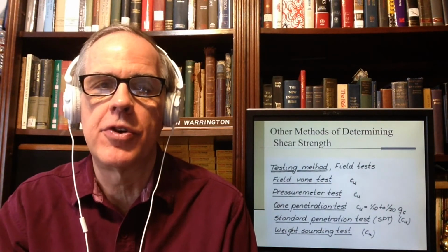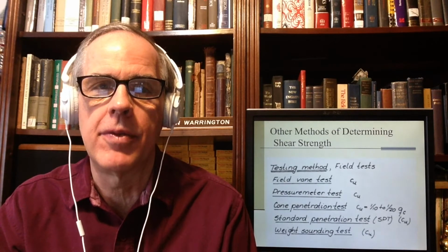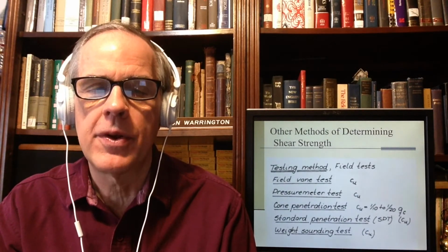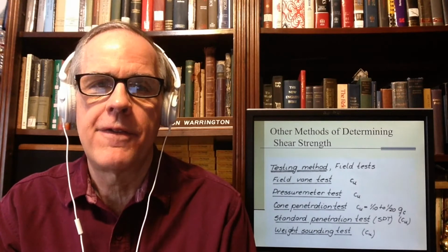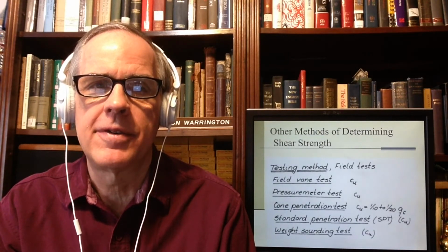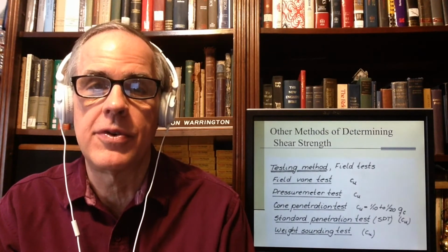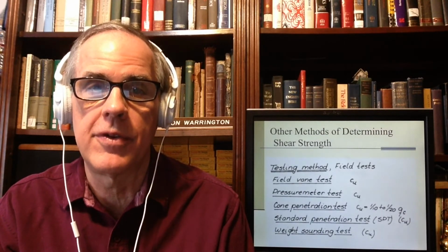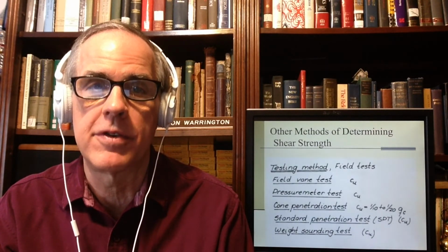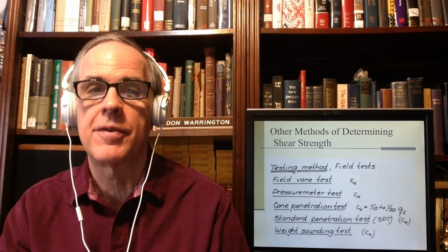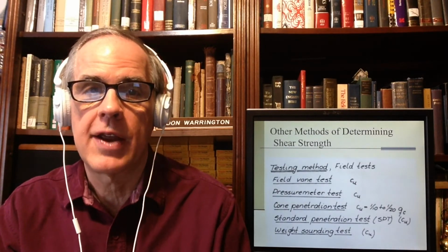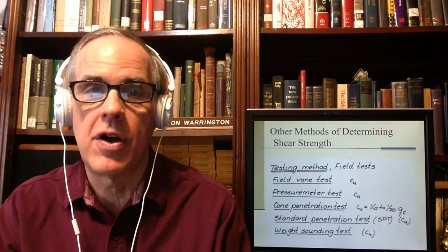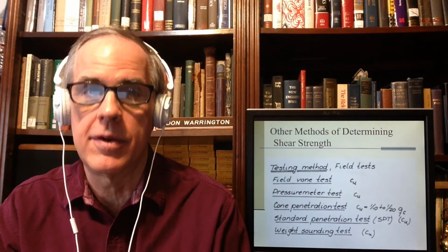There are other methods of determining shear strength, and we're going to talk about some of those. We're going to shift more to in situ tests. If you can accomplish the same thing with an in situ test that you can with a laboratory test, you're better off with in situ because of the sample disturbance. All the tests I've talked about up to now, direct shear, triaxial, unconfined compression, all require undisturbed specimens.